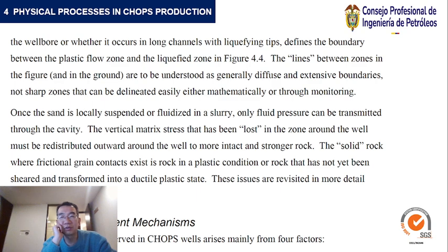The lines between zones in the figure and in the ground are to be understood as general, diffuse, and extensive boundaries, not sharp zones that can be delineated easily either directly or through monitoring. Once the sand is locally suspended or fluid in a slurry, only fluid pressure can be transmitted through the cavity.